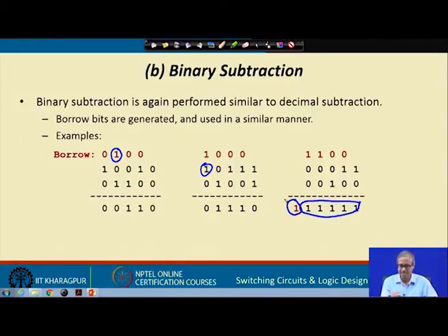So, you see binary subtraction is a little more complicated because the rule for the borrow is not as easy as in the case of decimal subtraction. So, what we try to do is avoid subtraction altogether. If we use 1's complement and 2's complement, we can do subtraction using addition only. We do not need to remember how subtraction is done. You can see that would be pretty nice. This kind of complex rule you do not have to remember anymore. Okay. Let us see.